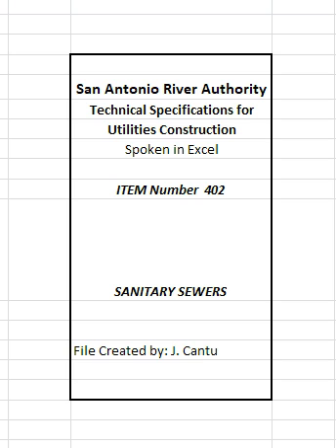Deflection tests shall be performed on all flexible and semi-rigid pipe. Any flexible pipe having a deflection of the base inside diameter, as defined in ASTM D3034, ASTM F679, ASTM F789, and ASTM F794 closed profile, greater than 5%, after installation will not be accepted.